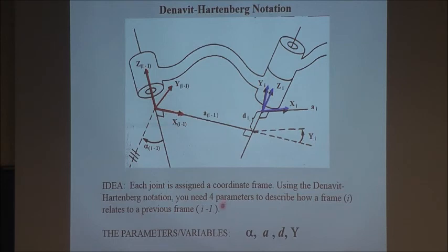minus 1. So these DH parameters are the specifications that come to the robot dimension. Okay. If, for example, the robot is built to have, let's say, 5 revolute joints and 1 prismatic joint, then you have in the spec sheets some parameters like a and d, which are distances, and alpha and theta, which are revolution and angular position.